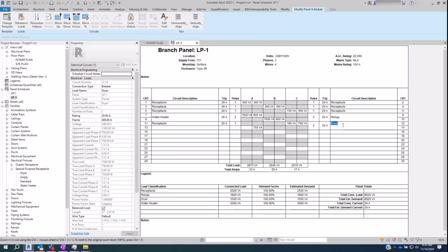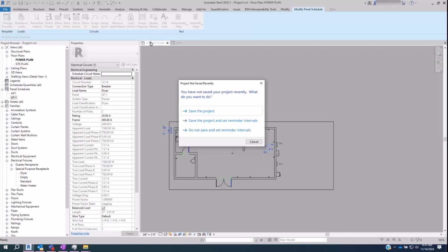Because we're not using anything smaller than a number 12 gauge wire, and remember, you're protecting the conductor between breaker and load. You've got to size the conductor and then size the breaker. And since we're using 12 gauge and nothing smaller, it can handle 20 amps. Hence, we use a 20 amp breaker. Mathematically a 15, but size wise, what makes the most sense for this project would be 20.